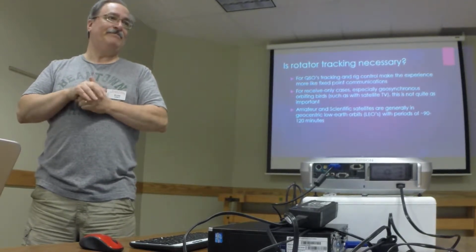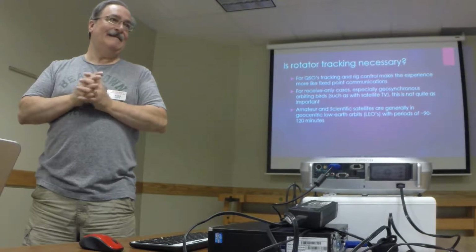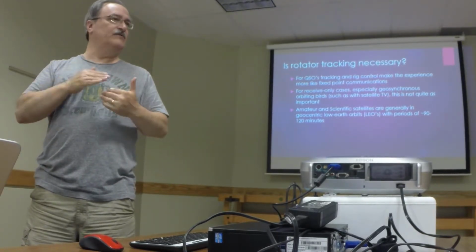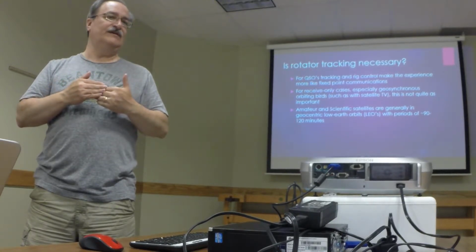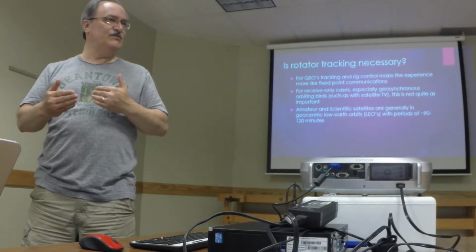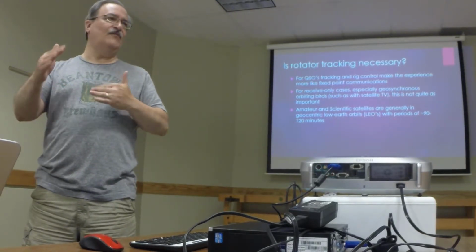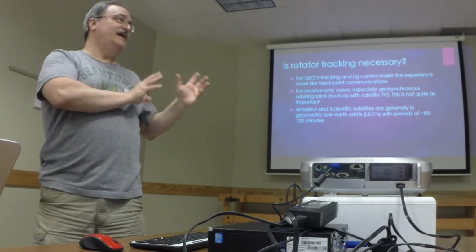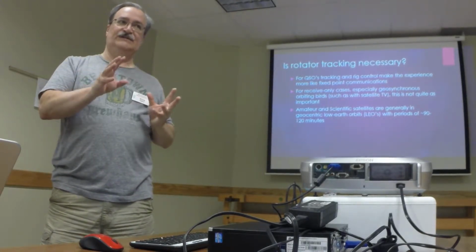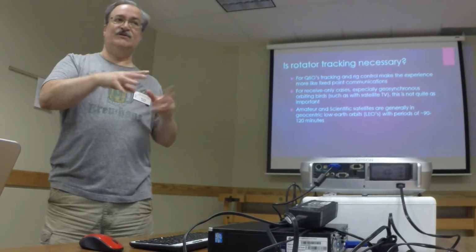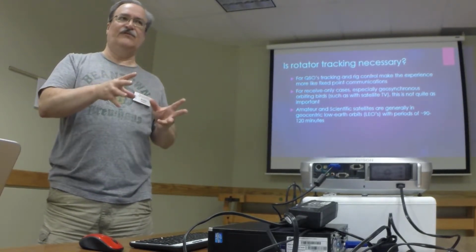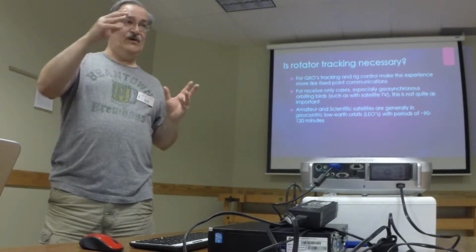And are they all in 450 to 460 megahertz? No, that's the UHF ones. They go a little lower, in fact, so they'll go down to typically about 436 megahertz for the amateur. They're all in that range for UHF. And then the VHF satellites are right near 2 meters. And if you're talking amateur, they're right on 2 meters. They're usually at 145 or 146, but typically 145 megahertz and above.